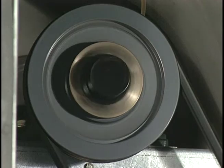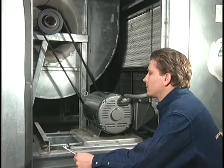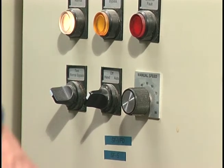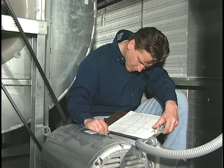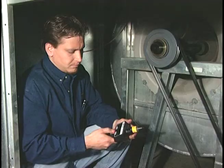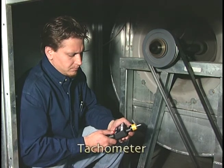With the fan turning in the proper direction, the technician listens and looks for any undue noise or vibration. If excessive noise or vibration is detected, the technician will immediately shut the fan off, determine the problem as best as possible, note the possible cause on the data sheet, and then report the findings to the appropriate responsible person. If there are no problems, the technician takes speed measurements on the fan using a tachometer.